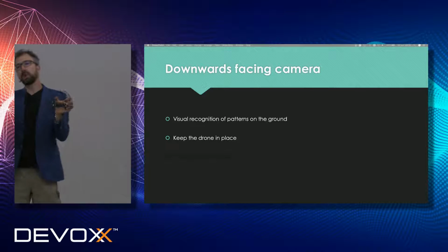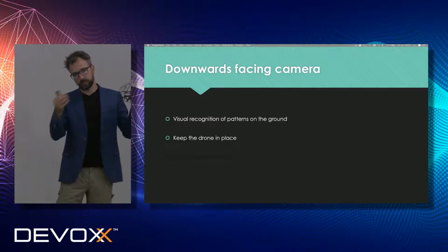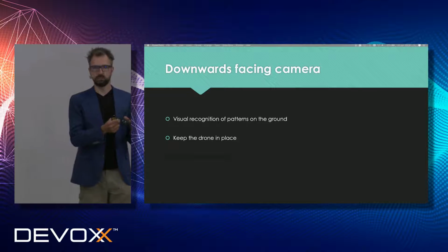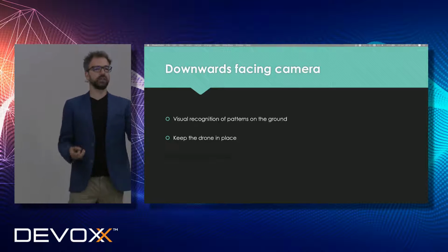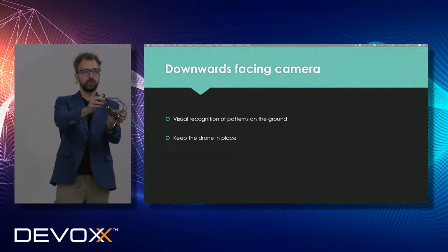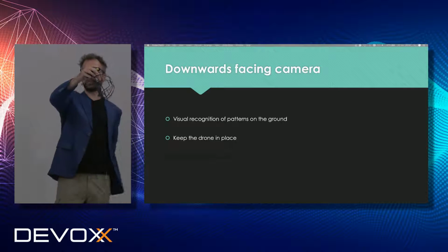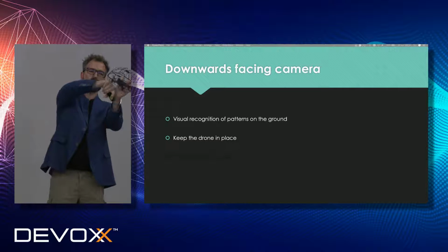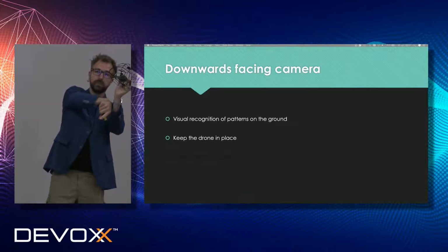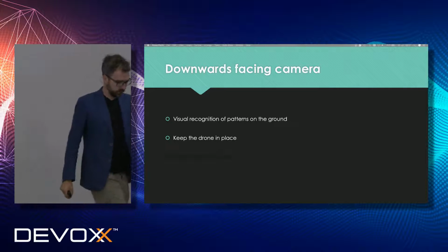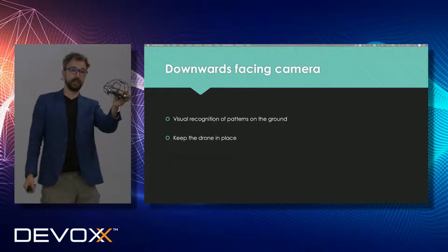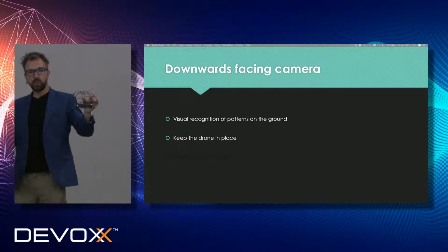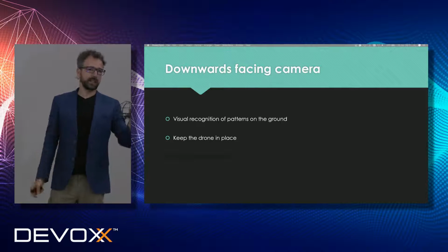Now, the big problem with helicopters or drones or any of these kinds of non-airplane aircraft is that they are very unstable. There's no reason for a drone to stay upright. So it will just as well hang like this or this. And if this happens, you see that the thrust is no longer pointing downwards, but it's pointing that way. So this is how a drone actually moves, by doing like this. You probably saw it when you saw a drone fly. But the drone doesn't know whether it's exactly upright.